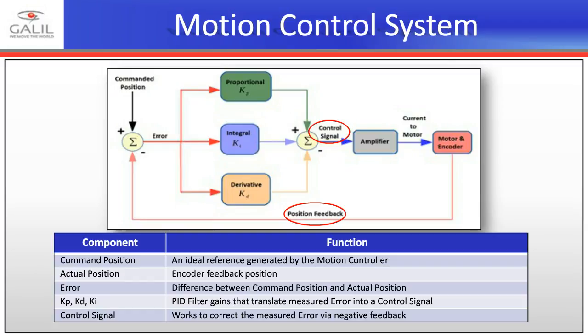Benefits of Ethernet: easily upgradable. You can take a component out, plug another one in, plug the Cat5 Ethernet cable in, you're good to go. Simplified wiring, since only one communication line is needed. And the communications hardware can be very noise immune with differential signaling and shielding.